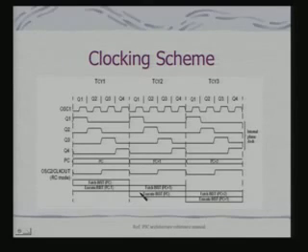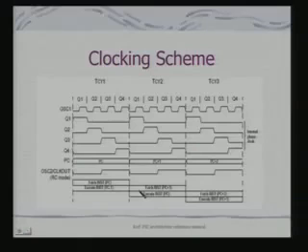Now, execution of this instruction would essentially mean a data movement from your register file. That movement would take place on your data bus. So my program bus is free, so I can fetch an instruction. What am I fetching? I am fetching the instruction at PC plus 1.